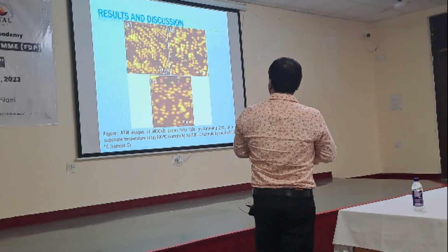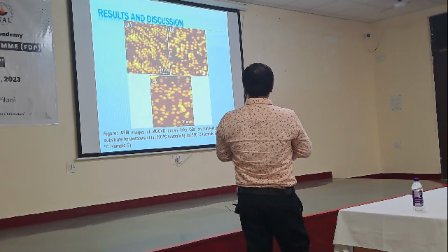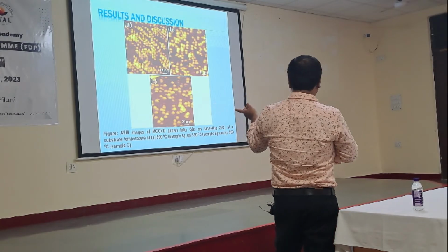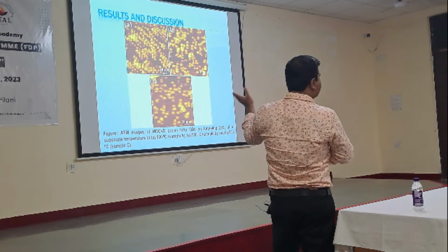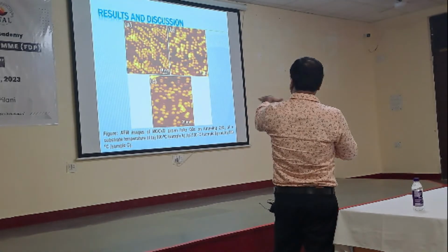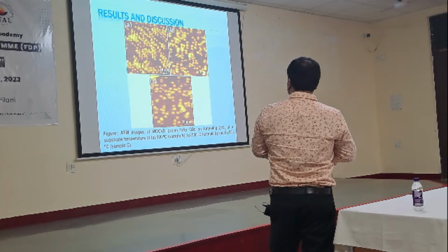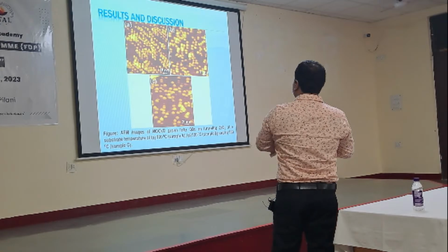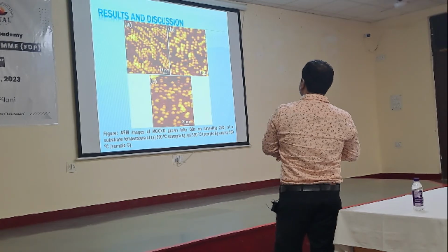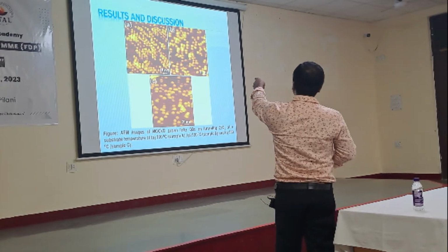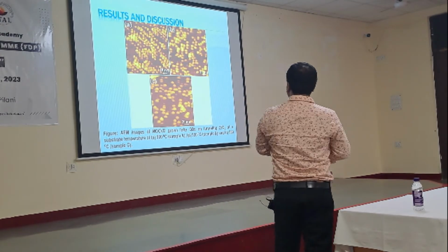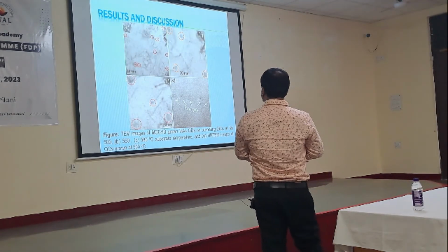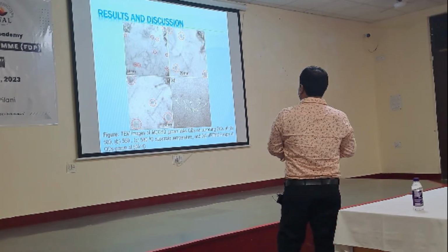Next, these are AFM images on tunneling zirconium oxide. This is a growth study. Previously it was on gallium arsenide, and now it is on a dielectric, tunneling ZrO2. This one is 500 degrees centigrade, this one 550 degrees, and the later one is 580 degrees centigrade. In all the cases, the sizes are in the range of 5 nanometer, 12.5 nanometer, and 16 nanometer. Next, these are the corresponding TEM images of the material I showed previously on the ZrO2 substrate.